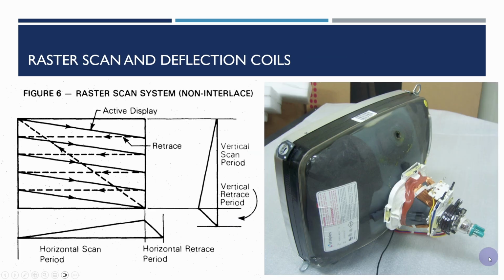Now, the key thing is that the TV picture is made up of these lines, by what's called a raster scan. In general, the electron beam comes from the electron gun at the back of the TV tube here. There's generally a very high voltage, probably 20,000 volts plus, between the cathode here and the anode of the screen here. This means the electrons get fired at the screen, and these deflection coils will scan the electron beam across the screen.